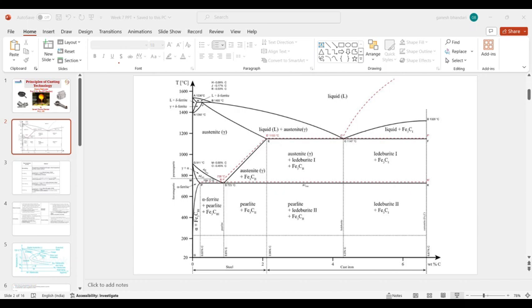When we talk about some specific applications, like a gear assembly, we need some hardness at the teeth of that gear. For providing that higher hardness value, but we need ductility inside your sample. So we just need that property of higher hardness at the surface itself. To provide that surface hardness, we generally go with surface heat treatment processes.